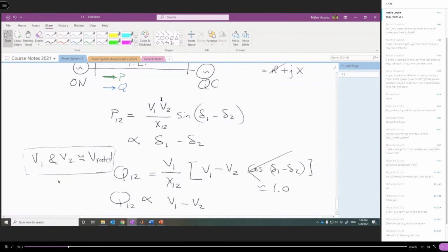So if you double the voltage of the transmission line, we can increase the amount of power by 4 times, which is 2 squared. So if you double the voltage, the maximum power transferred, which is calculated by this factor, will be increased by 4 times.